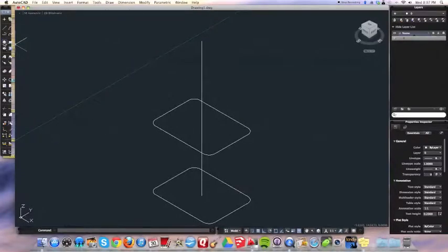So I'm going to create some circles for that. I'm going to go to circle radius. I'm going to start on the bottom because I want to move it. I want to make sure it's along that center point. So I'm going to click the center of the line, and let's go out. Diameter 0.5 seems like a good measurement. And all I did was go out 1 square on the grid, and I'm going to move that.